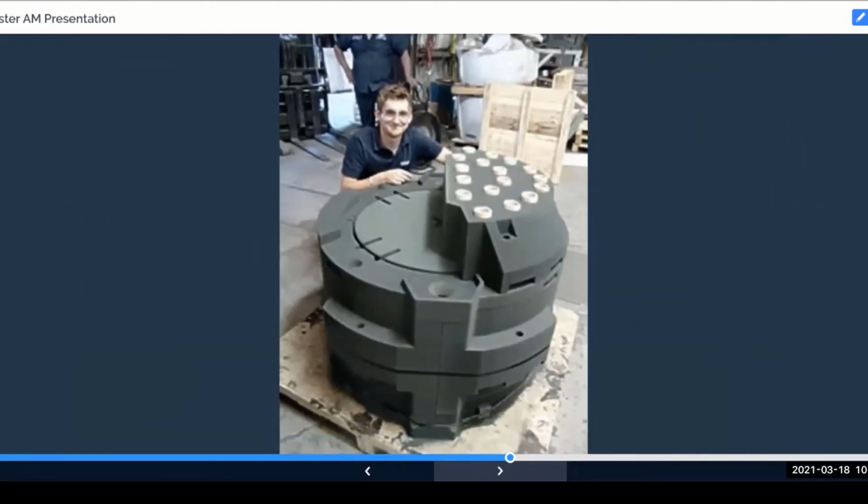But the thing that you guys maybe are more interested in, or should be more interested in, is what they've been able to do with sand. They're gluing together sand to make sand casting molds. Here's an incredibly complex mold. Because they don't have to get a positive out as they're printing, they just have to have drain holes for the loose sand to come out, they can make incredibly complex geometry and then glue together these parts.